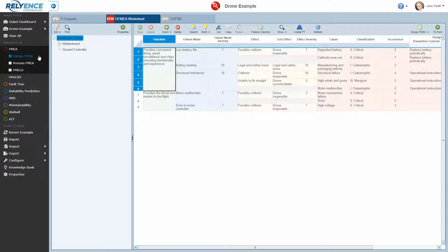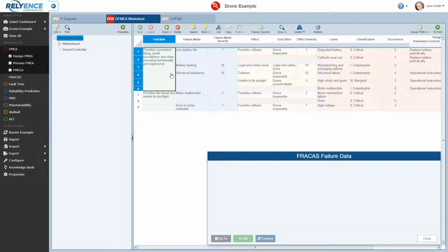In the Using Failure Direct Connect in Relyence FRACAS video, a FMEA data add request was made using the Failure Data widget. The FMEA component of the Relyence Failure Direct Connect feature allows FMEA team members to review items that were added by the FRACAS team. Recall that we added the DFMEA Failure Data widget for this example, so make sure DFMEA is selected. And from the toolbar, here in the DFMEA worksheet, click Insert and FRACAS Failure Data.